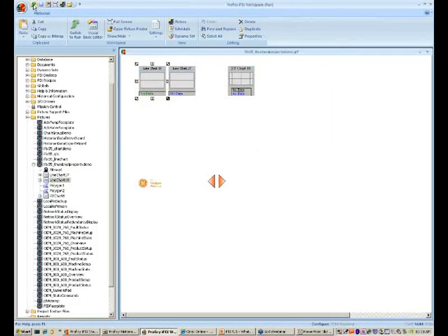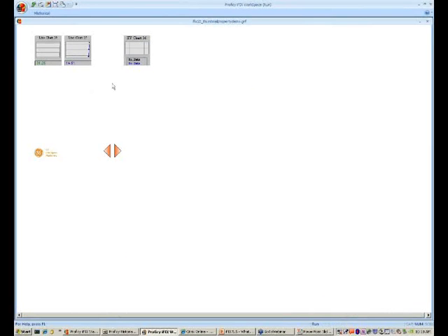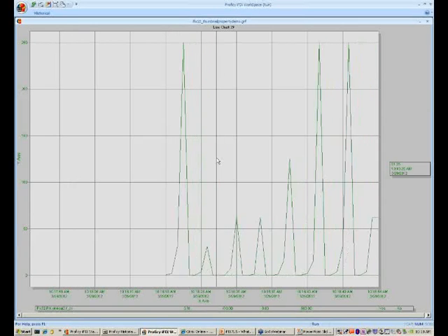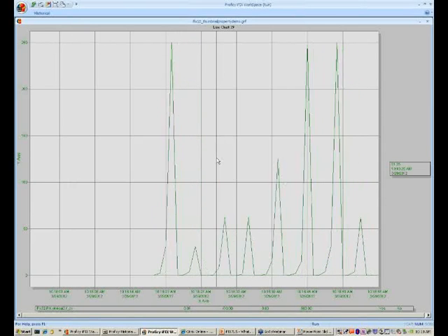So if I put this into my run mode, the first thing that you would observe on the thumbnail is that it takes away all of the remaining legend, and it just puts the value of the pen or values of different pens that are being plotted. Now, if I enable the quick configure mode, as I move the mouse on the chart, it comes up with this option automatically. It's part of the chart object, so there's no additional scripting that is written, but it comes up with this option on the right-hand side of your chart, and when you click on it, it basically goes into a full view of the chart.